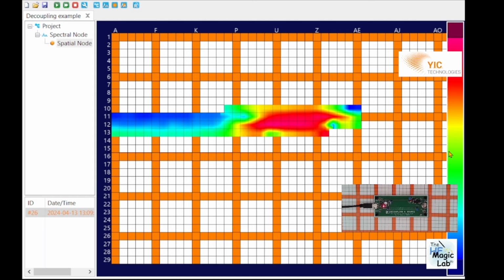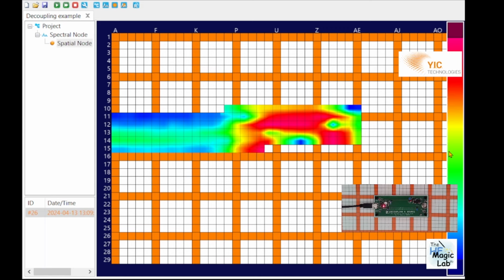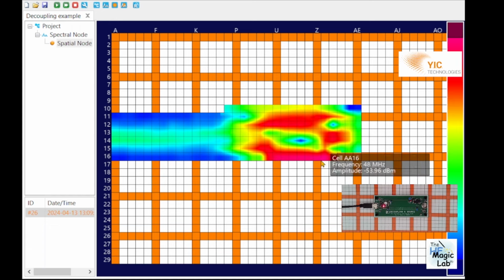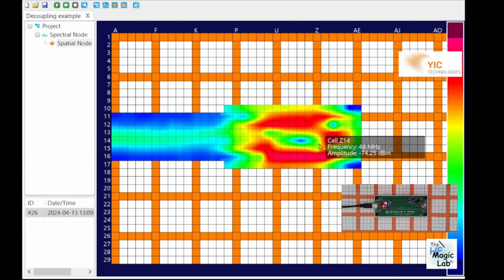We can start to identify how in my PCB I have a loop. This is the loop we were explaining at the beginning of the video. No? So the energy is basically taking, the high frequency current is taking the full area of the PCB. And that was the problem created in power integrity and that was solved by the decoupling capacitor.